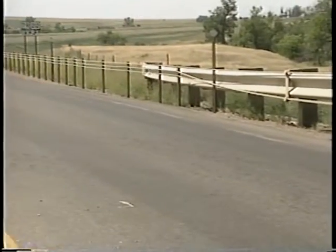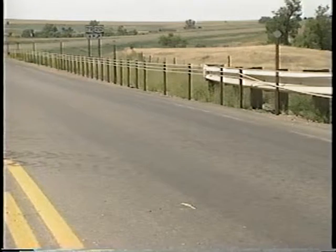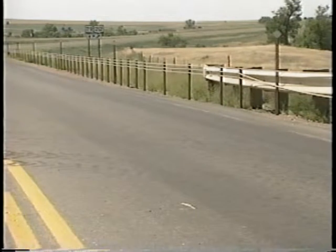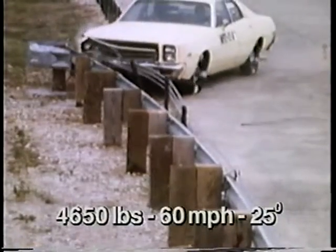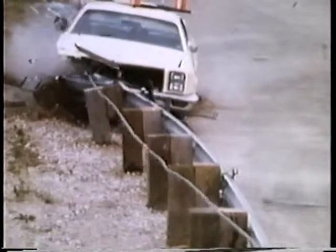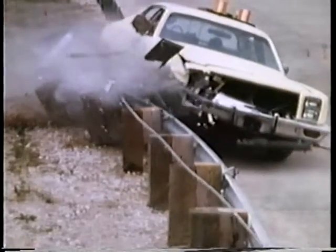The post spacing of the cable system is reduced near the transition, and the cables are passed over and under the W-beam to a concrete anchor buried behind the W-beam's breakaway cable terminal. The large car strikes the cable system and deflects about 4 feet before it strikes the end of the breakaway cable terminal. The vehicle quickly redirects after striking the W-beam system.